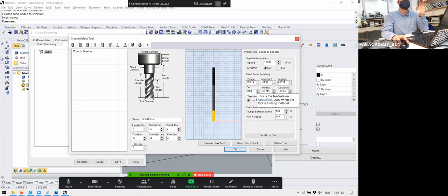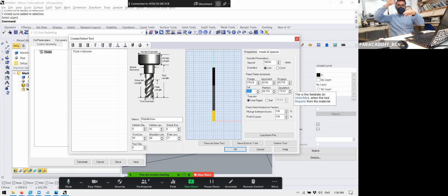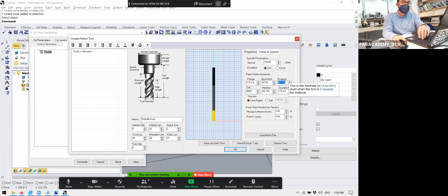So in here we choose cut. What is plunge, approach, engage, retract, departure? The name states it a little bit. One thing is cutting, but to reach this direction, we first need to get down, then make a little turn, and then accelerate. So it's plunge, approach, engage, cut. The rule I use is 2/3 of the cut speed for all of them. In general, for woods, unless it's aluminum, that changes, but it's a little bit of accelerating. It could be more or less this plunge.